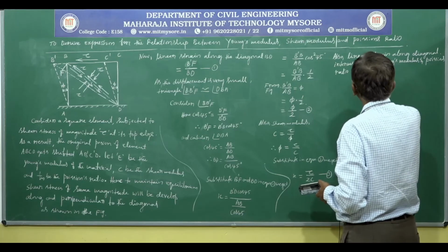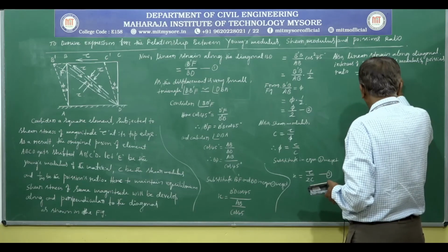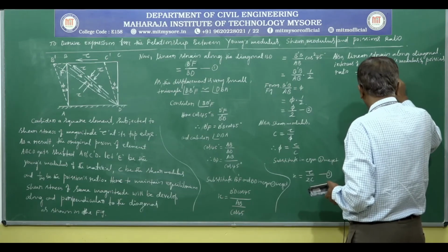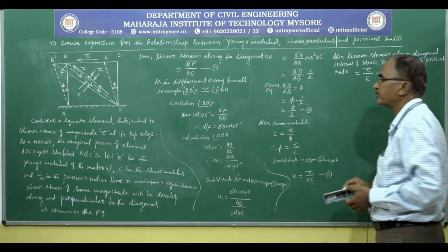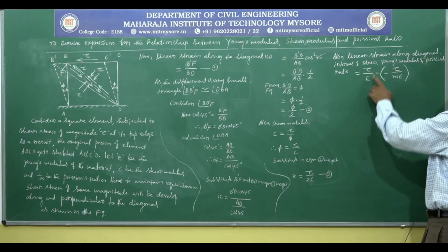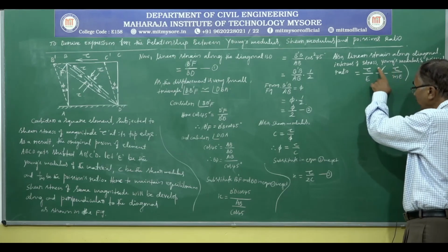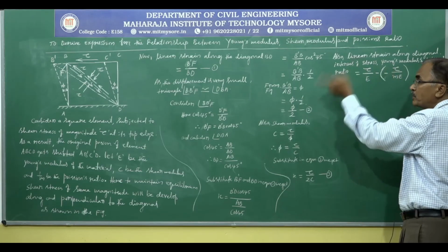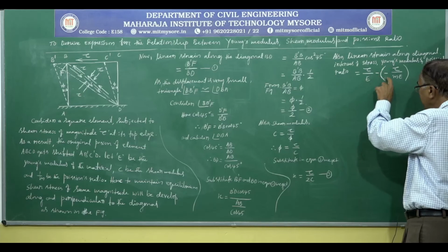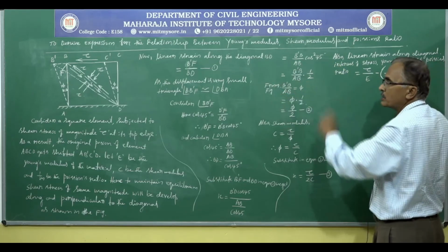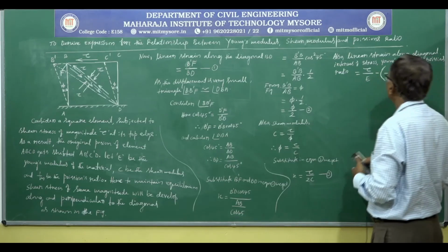That is equal to tau divided by E, the longitudinal strain, minus of minus tau divided by mE, the lateral strain. Lateral strain is always opposite in nature to longitudinal strain, hence this negative sign. Further, one more negative sign is inside the bracket, since the stresses are compressive in nature.